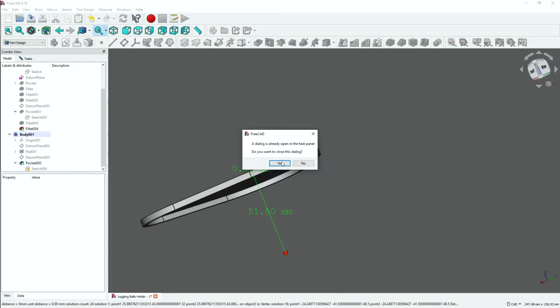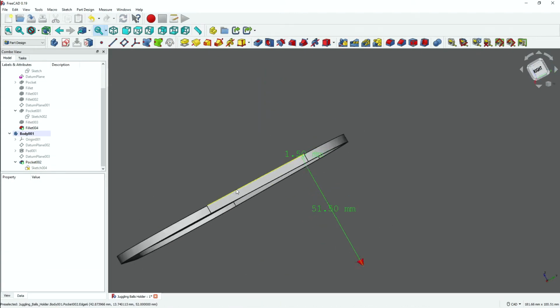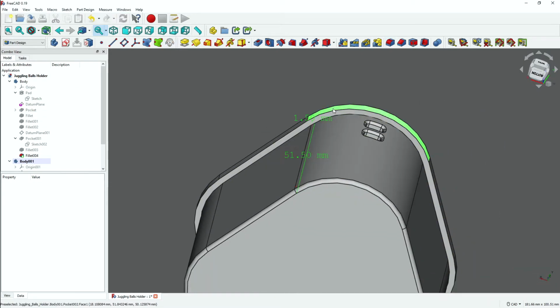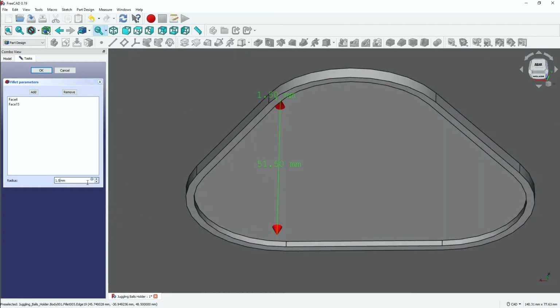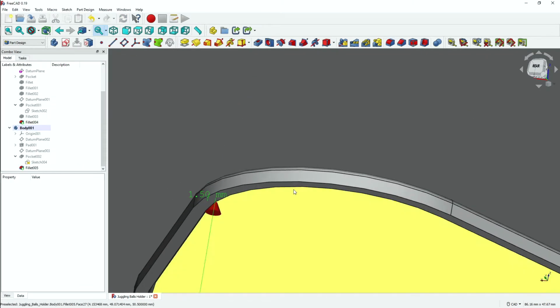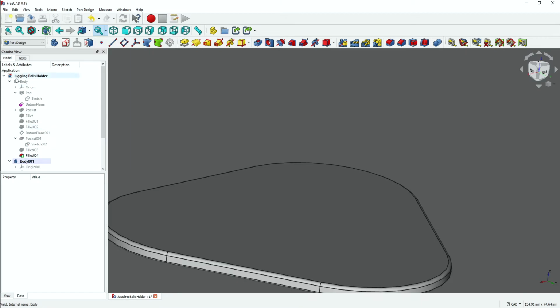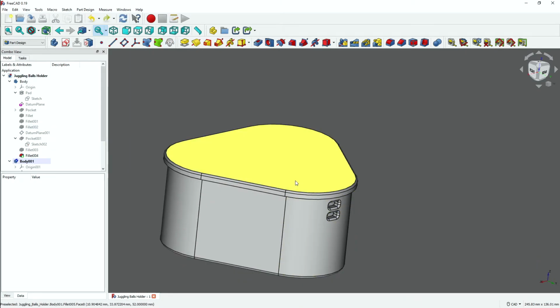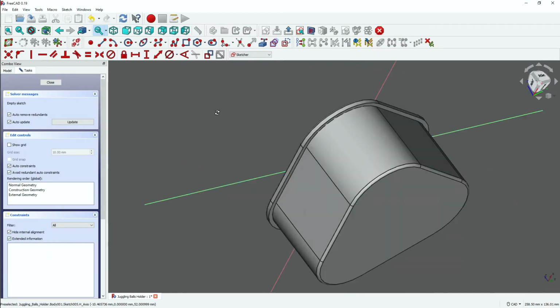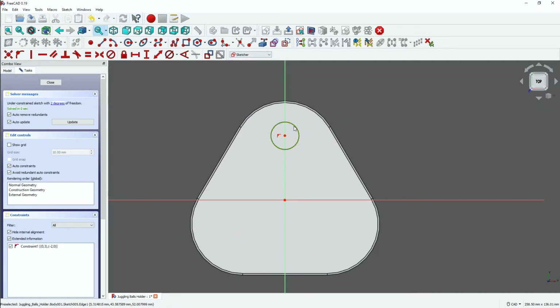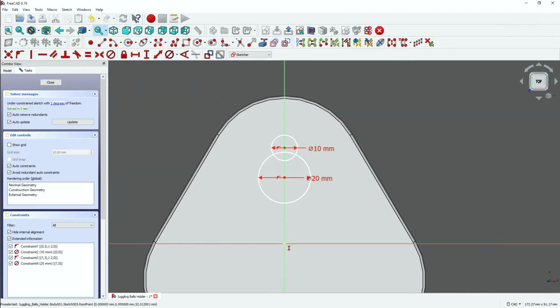So eventually I start to fillet in different places, and filleting is kind of fun in this, as in it's a little difficult. It's not that difficult, but it's just not intuitive. All the other features I've been using, I can select the tool and then select the edges or faces or whatever I'm doing. But for fillets, they want me to select everything that I'm going to fillet and then select the tool. It's like the opposite of everything they're teaching you.